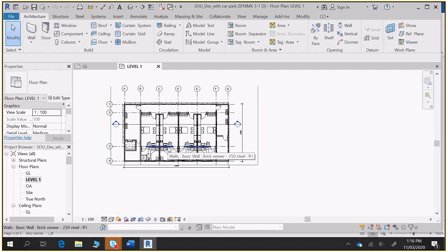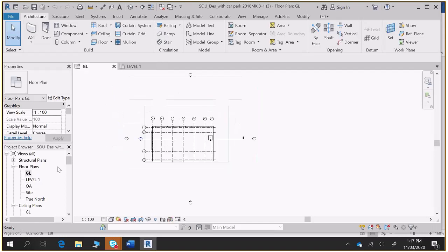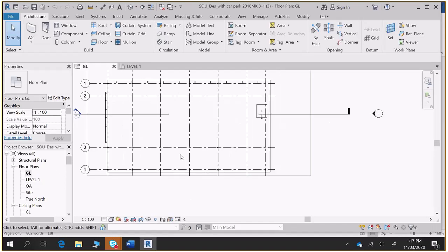So that means we can't move that one. Well, you can. What you'd have to do is put in large lintels. At your ground level, if I zoom in, you've got columns here, transferring load down to footings. So think about your columns.